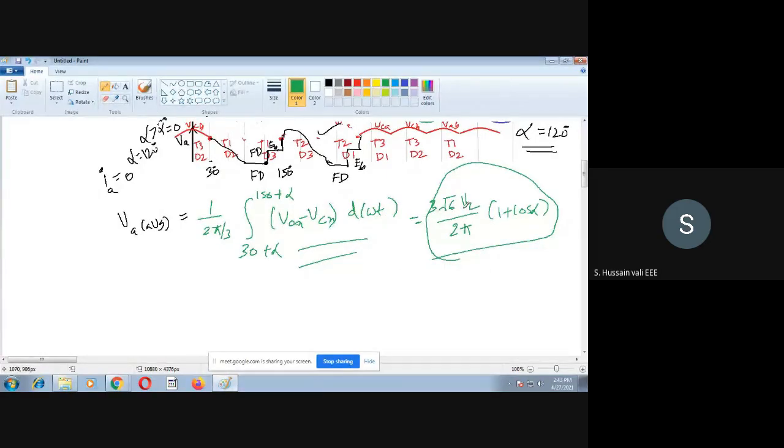And then what else you will find out is that this is VA. As you know already, VA is equal to EB plus IA RA. EB, back EMF, in this case is some K into N, because this is a separately excited DC motor.